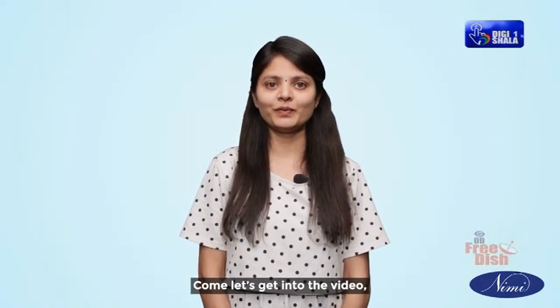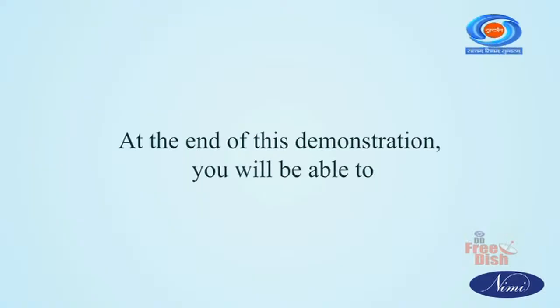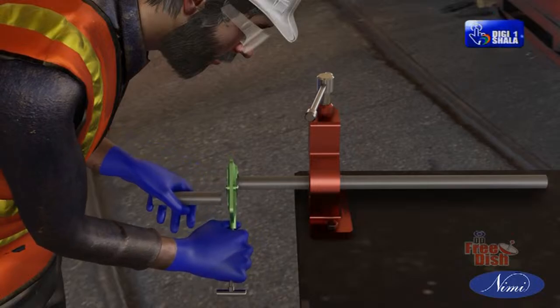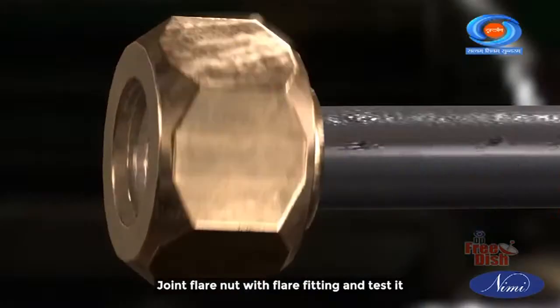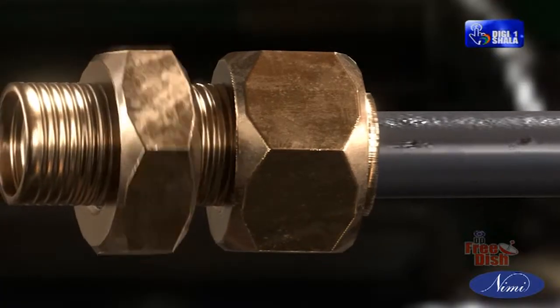Come, let's go into the video. At the end of this demonstration, you will be able to cut a GI pipe using a pipe cutter, remove burrs using a pipe reamer, flare the end of the pipe, join the flare nut with the flare fitting and test it.